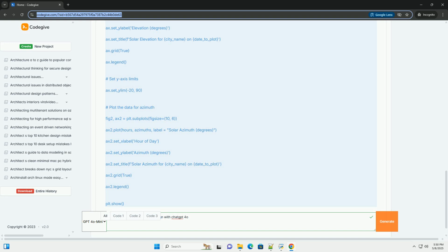Possible outcome from ChatGPT 4.0: 1. Facade articulation with vertical elements: introduce vertical elements such as fins or louvers to break up the monolithic concrete facade. These elements can be constructed from wood-look composite material or colored metal, creating a dynamic interplay of light and shadow. Angled fins can also provide shading, enhancing energy efficiency. The color palette should shift from a uniform gray to a contrast between light gray for the main surface and darker shades for the vertical elements.